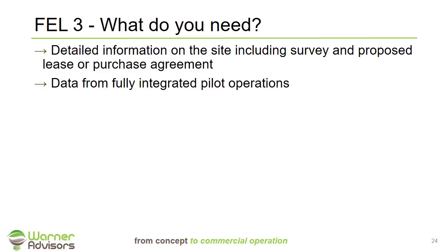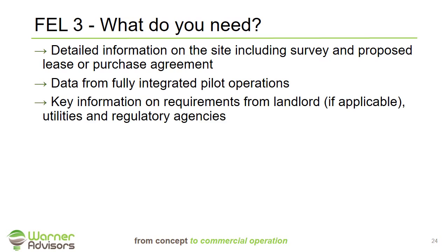In earlier versions, I've shown where key information is going to be needed to get budgetary estimates on the equipment. In the case of FEL3, the level of engineering detail required is going to require data not only from running the different unit operations, but running them as a fully integrated unit so that there's time for impurities and other materials and recycle stream to work through and generate representative data.